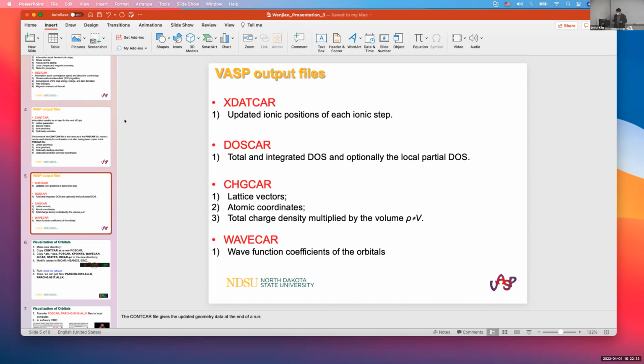They use the literal definition of the number of states per energy interval, which will work only if you have like 1,000 orbitals. If it is less than 1,000 orbitals, the DOS composed from DOSCAR will look very ugly. It will have sharp edges and more gaps. So it is good for big systems, but will not work for small test systems.